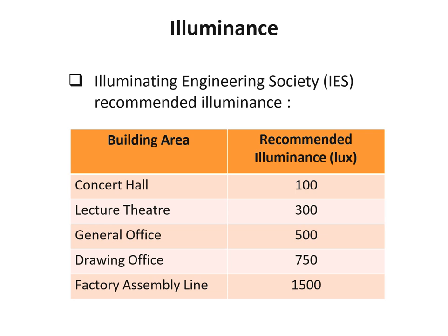And for the office, it will branch off. Sometimes it branches off into specific functions, like if it's for drawing, like a studio space, or an old, traditional kind of architectural office where you still rely on physical drafting. Then the recommended illuminance will be elevated, it will be 750.